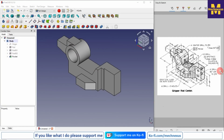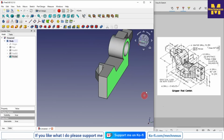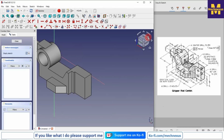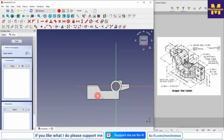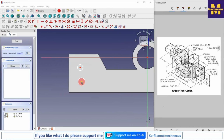Now our next feature is to create a hole of 6 drill, 82° CSK to dia 9. So for this we will select our back face and click on the sketch, switch to the isometric, and we will rotate our model. And now here we will create the two circles, and now we will give our dimensions. So from this edge to this center is 22.